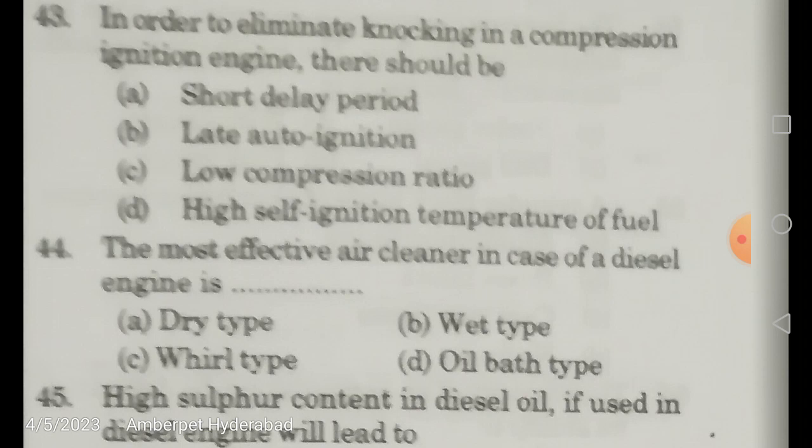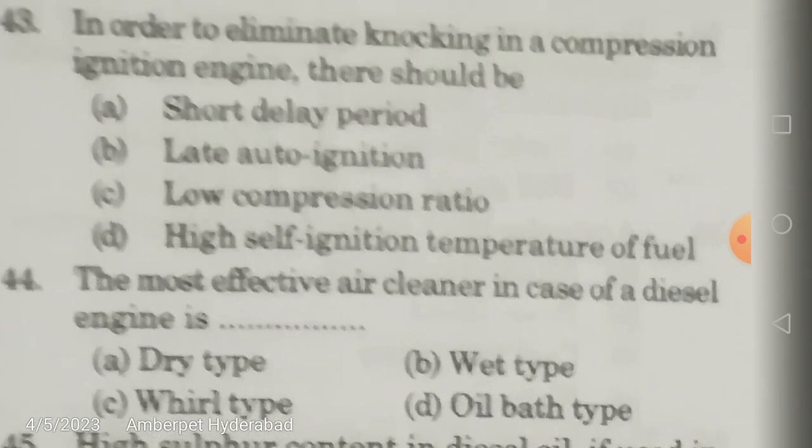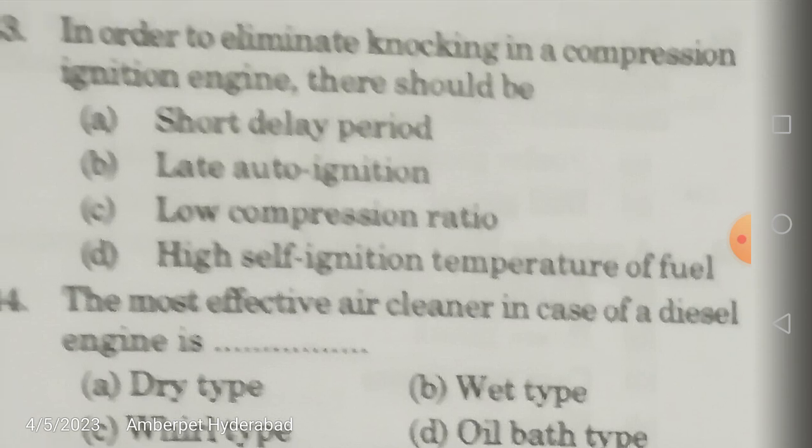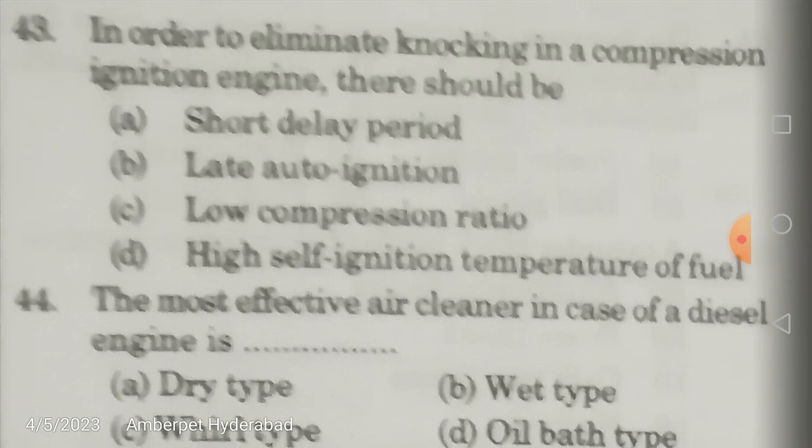But what is knocking? It is the uncontrollable pressure rise on the expansion stroke in an engine. Okay, so what is the correct reason for this? The correct reason for this is short delay period.